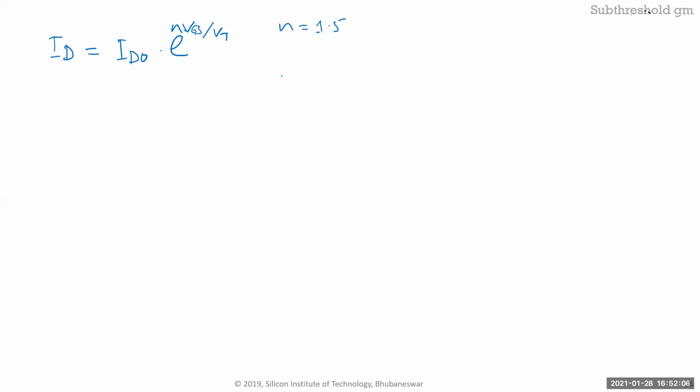So when you're in subthreshold, it actually looks like a BJT, but it's 50% worse than a BJT, which is still much better than a square law, in the sense that current gain to voltage input is exponential, whereas in saturation, it's a square law. So the amount of current change you get in the exponential way is still better, even if N is 1.5, compared to a BJT.